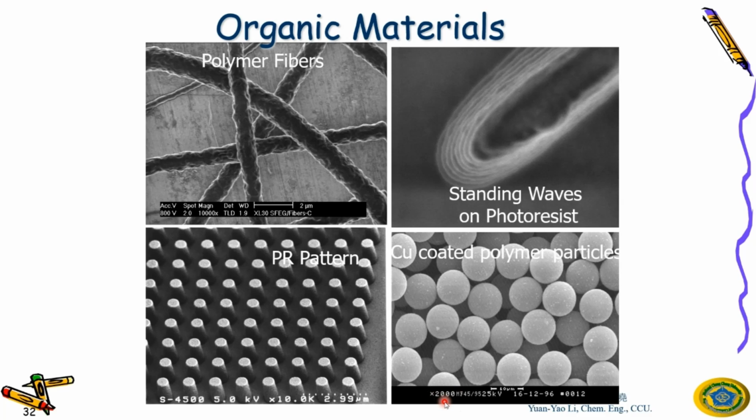Okay, let me show you here. This is the scale bar. From here to here is about 2.99 micrometer. And the magnification is about 10K. 10K is what? K is 1,000, right? So it's 10,000 times larger. Okay, and this 5 kV is what? 5,000 volt. That's the voltage.